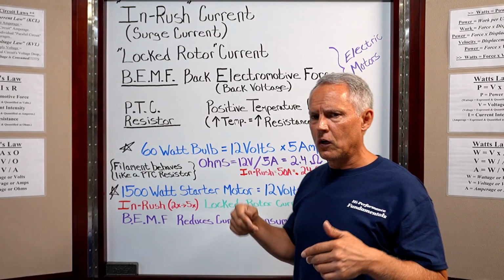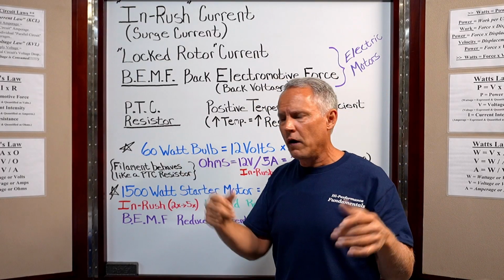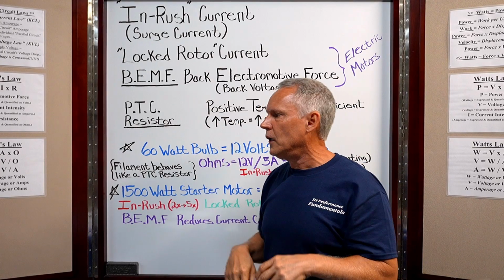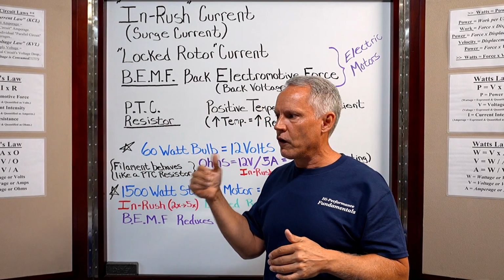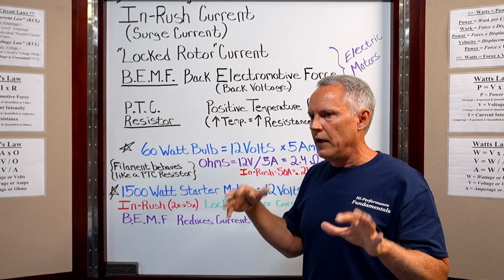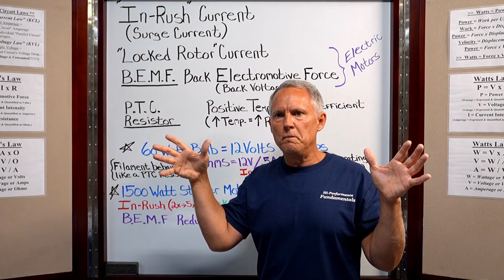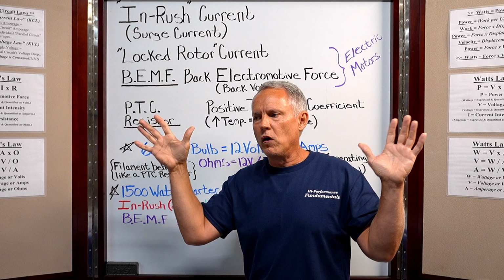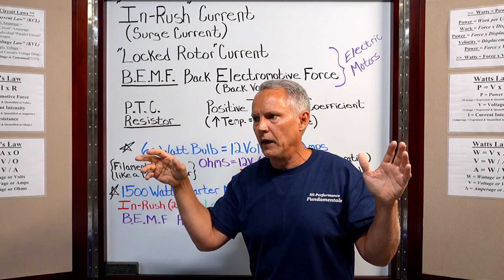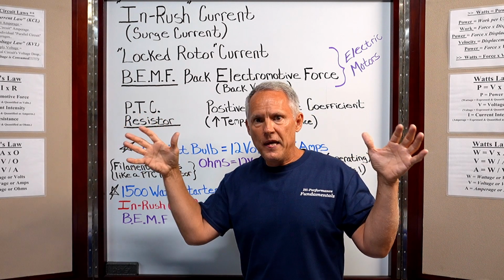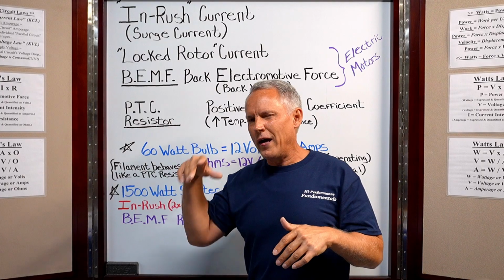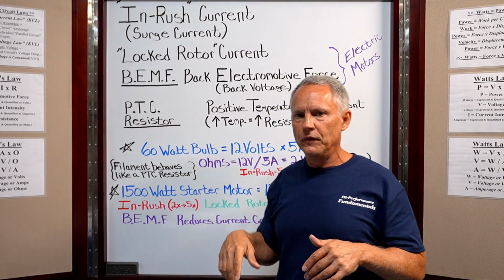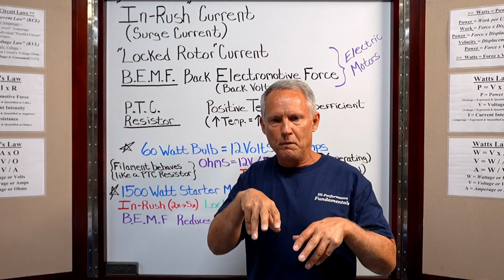But until the car is assembled, you got the engine in the car, starter motor attached to the engine, the actual engine that's going to be in the car, right? It's hard to test current flow through that starter motor because, as an example, if the engine itself is a big, large displacement, 500 cubic inches, 14 to 1 static compression, big race motor, it's going to create a lot more resistance to that starter motor rotating than it would if it was a 4-cylinder engine with low compression.